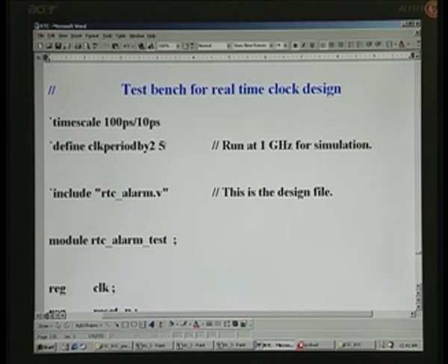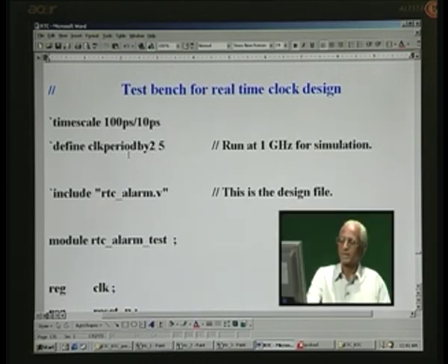If you put 5 here, it means 500 picosecond, and this is on time, and likewise equal number will be for the off time of the clock, and total what you get is 2 into 5, and that is 10 into 100, which is 1000 picosecond or 1 nanosecond. So, if you take 1 nanosecond, it is nothing other than 1 gigahertz, and that is how you fix the frequency in this fashion.